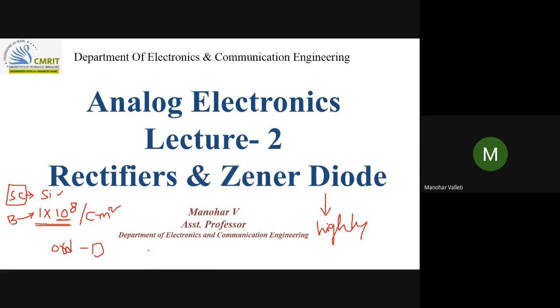In the same way, if I am saying 1 in 10 power 5 of the same boron atoms, what is the meaning of this? 1 boron atom for 10 power 5 silicon atoms. So let us say this is 1, this is 2. Tell me which one is the highly doped concentration? Whether 1 is more doping or 2 is more doping? Yes, 2 is more doping, because 10 power 5 silicon atoms are sharing only 1 boron atom, whereas here 10 power 8 silicon atoms are sharing 1 boron.